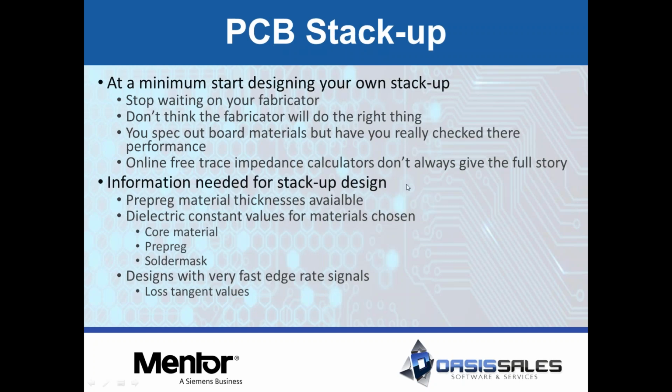So PCB stack-up is another one that you should be playing with. Don't wait for your fabricator. A lot of designers will go to their fabricator and say, hey, here's what I want to do. Can you tell me what my stack-up needs to look like? Or you just blindly create one, put it on your fabrication drawing and say, here's what you want them to do.